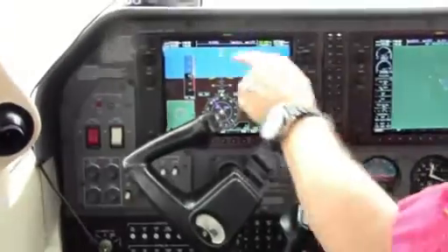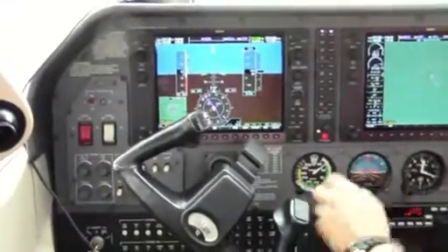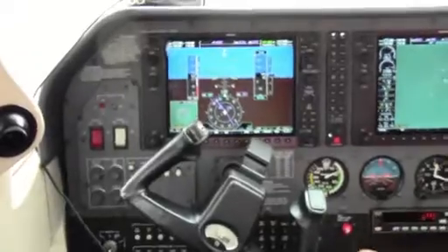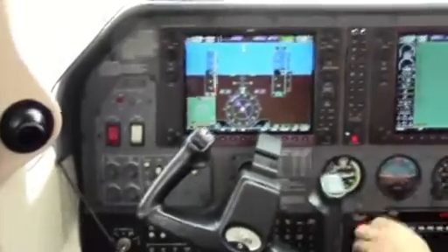As we accelerate on the runway, the crosswind correction should slowly be reduced. And once we become airborne, proper correction into the wind must be applied to avoid the drift caused by the crosswind. Okay, my friends, today we are going to practice a crosswind landing and takeoff here at the airport of Edinburgh. And that involves a specific technique to perform before we take off or before we land.